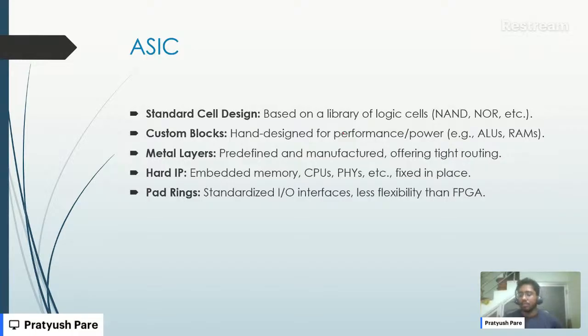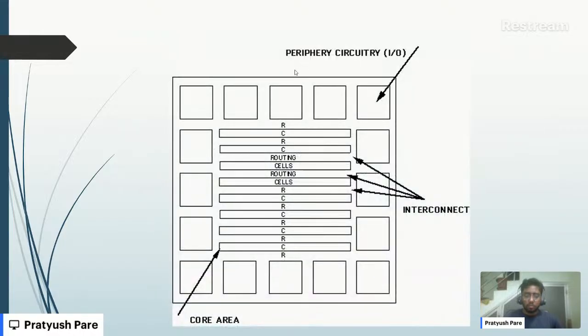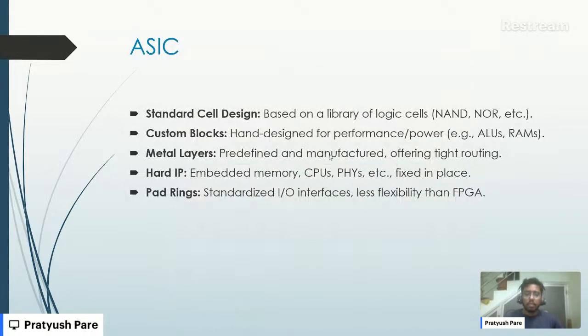No, no, it is not a logic zero circuit construct. It is an open node, so it will be in the high Z state. If you ever do simulations of something like that, you will see a Z state there. In Verilog, we have four types of states: a one state, a zero state, an unknown state, and a high impedance state.